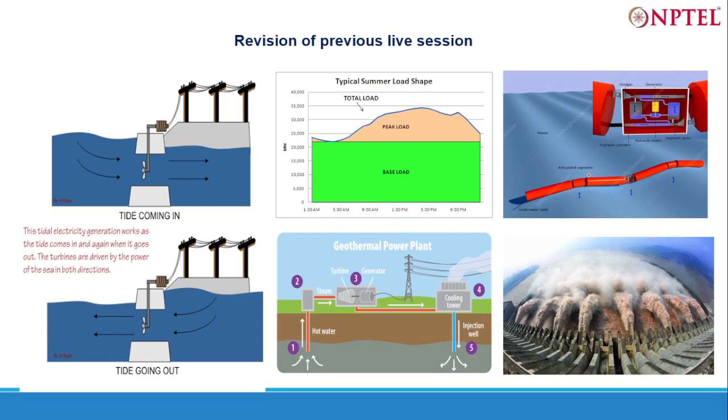Okay, in the Pelamis converter, there are some hinge joints to which these devices are connected, and in between these hinge joints we have the ram, turbine, and hydraulic fluid. So what happens when this moves up, this fluid goes here and this comes down. When this comes down, the fluid will go through this turbine and rotate it. When the wave passes, there is a crest here, so this will go down and push the fluid here, it will push the piston here and pass through the turbine. So that's how electricity is produced in the Pelamis converter.